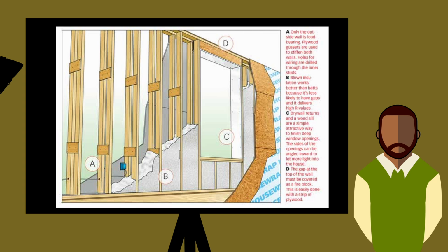I think it's like 19.2 inches. So usually standard studs are 16 inches on center. And if you increase spacing, then they could be 19.2 inches on center, and also 24 inches on center. And they do that for the plywood, the actual sheathing that goes on top of those. That's why those spacings are important. Don't just get out there and think that you can do whatever you want to do, right?